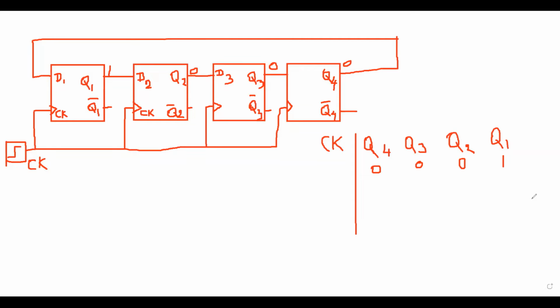Again, I remind you the work of the D flip-flop is data transmission. Whatever data we are giving to the D flip-flop, when the positive edge of the clock pulse comes, the D is given to the output. Here, as we are having a synchronous clock, we need to get ready with the inputs every time. So, to give the first clock pulse, first I need to get ready with the input.